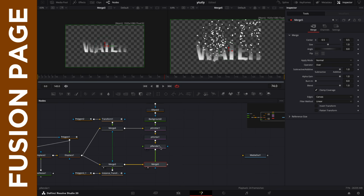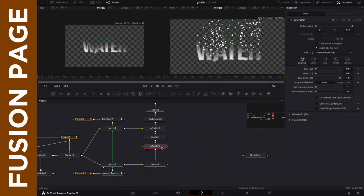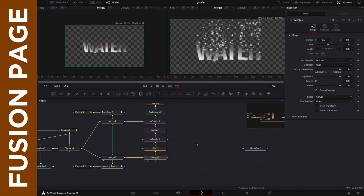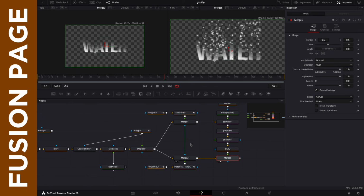So between this P render and this merge, I'm going to click on this P render. I'm going to bring in a blur node. Click on this blur node. This appears. Let's set this to maybe 5. Yeah, so that works. Now we want to give it the background, which is the video that we had initially.